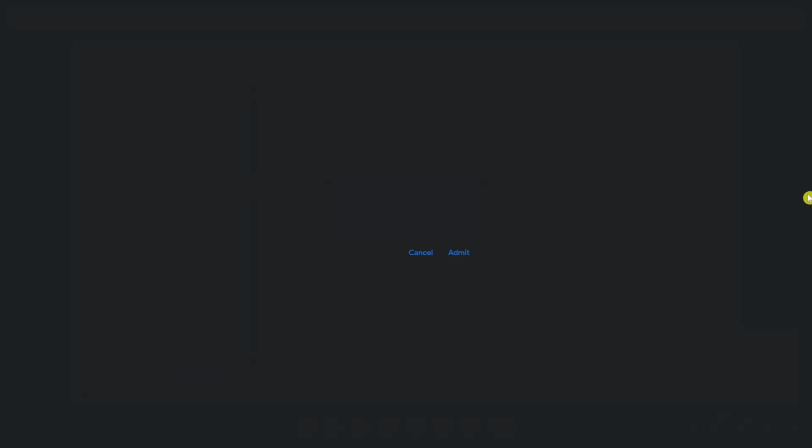And now you can see it takes a number of inputs, the first of which is elements. So we should ask what will be the element, which is the Revit element of whose parameters we are trying to set in this case. The answer is pretty simple. It is the rooms. We have already obtained the rooms at the first step, right? So we can just move this a little bit down. Take a connection from here. Taking a connection is very easy. You just click it and then drag it over here and connect it. So you can see it turns blue. So that means we have already got the first of the three inputs required for this node to work, which is the elements, which we know are the rooms that we already selected.